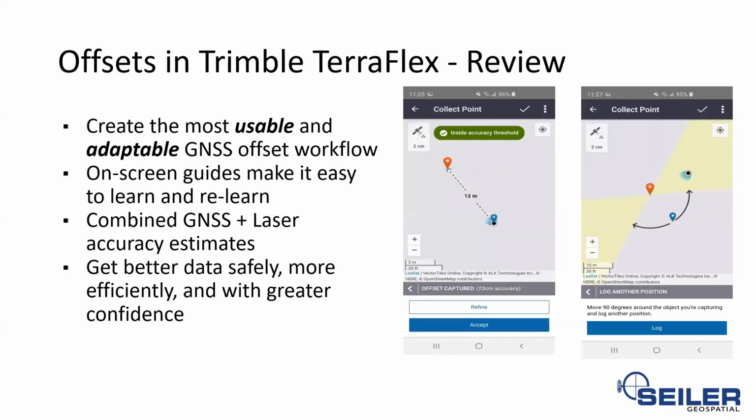In review, it depends on, again, which laser you are currently using. You kind of have 2 options with the 360. You can run it out as what it normally is intended for, the single offset with the bearing. Again, make sure that that compass is calibrated and that you're not standing near any metal objects, which is discussed within the YouTube videos on calibration and magnetic hygiene.